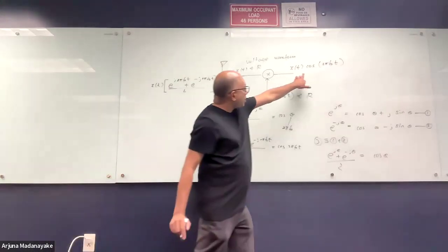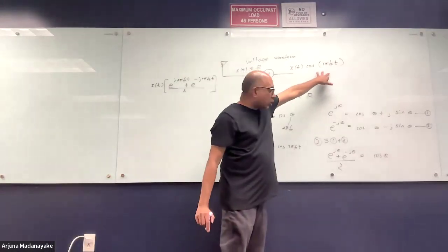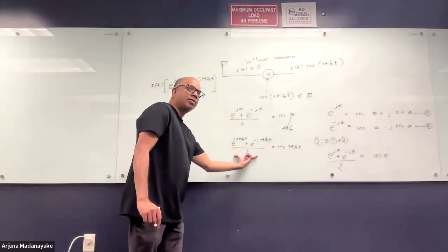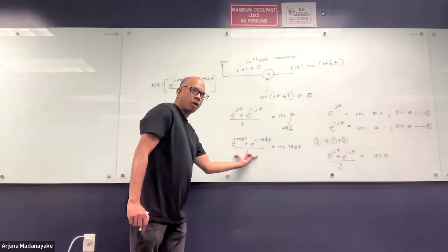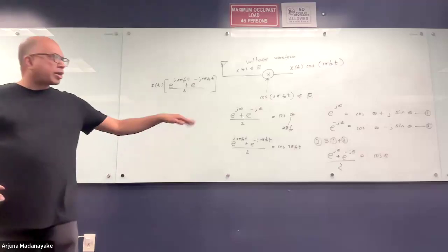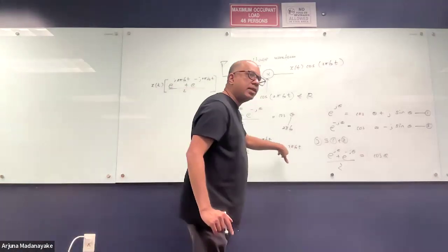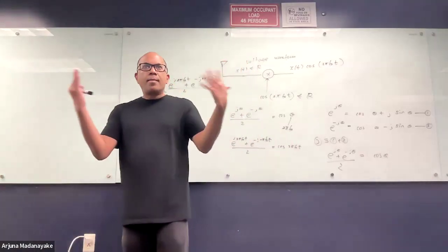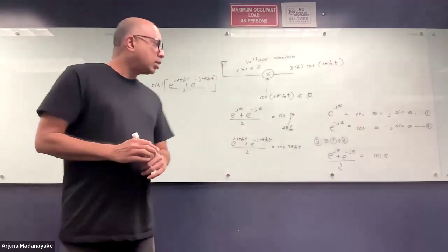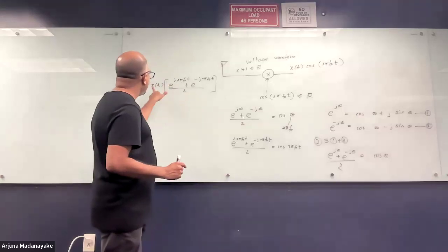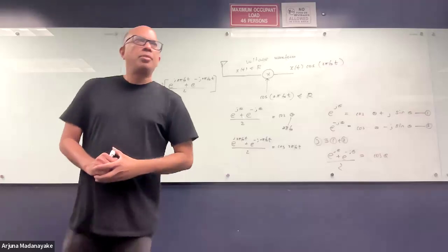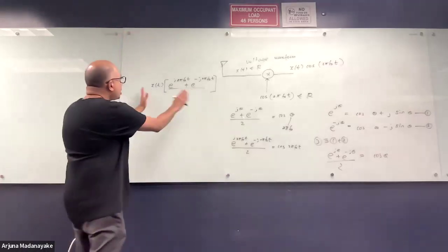I took the cos part and I chucked that and I plugged in this part in place of it, because that's it. Now we are in good shape, because now I replace this real valued cosine thing with two complex valued functions which we know how to handle from the previous theorem. We know how to model x of t times e to the j 2 pi f naught t. We just proved it 10 minutes ago. So this is actually 2 of that.